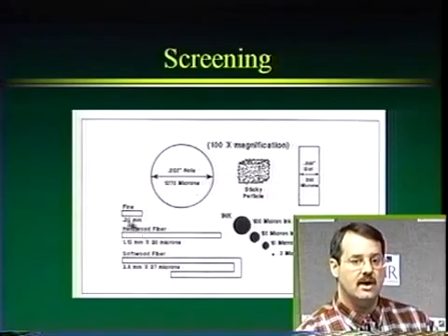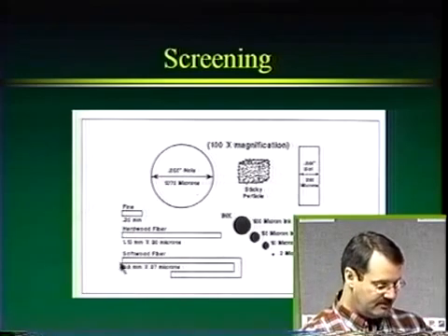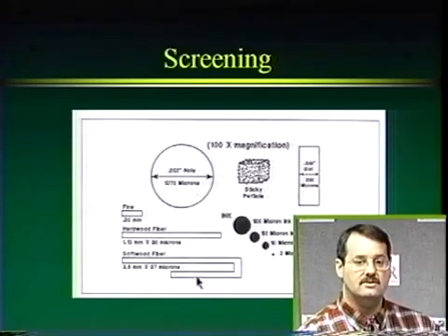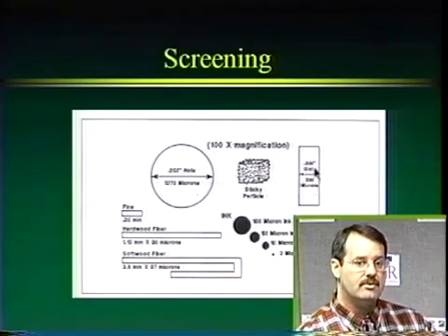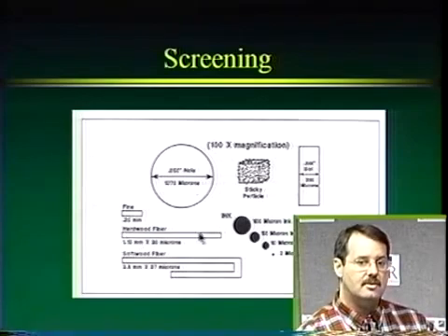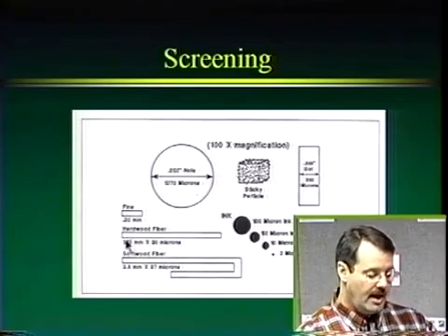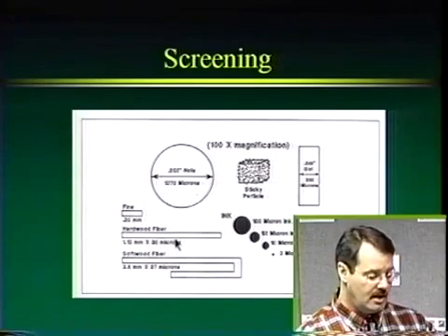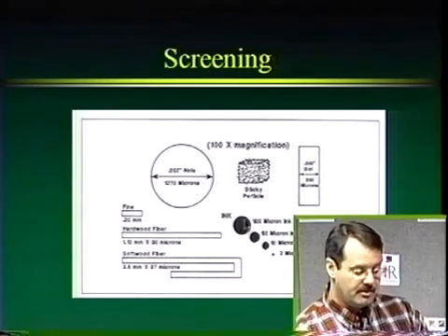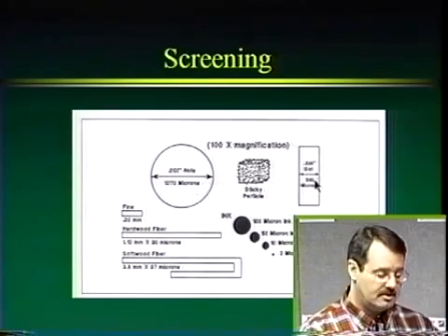Now here we have a softwood fiber, and that softwood fiber is about 3.5 millimeters long and 37 microns wide. And you can see that if it's aligned properly, it will scoot right through that slot. A hardwood fiber, a little bit shorter and finer, let's say a typical one, is 1.15 millimeters long and 30 microns wide. So that 30 micron wide fiber will easily fit through the 200 micron slot if aligned properly.